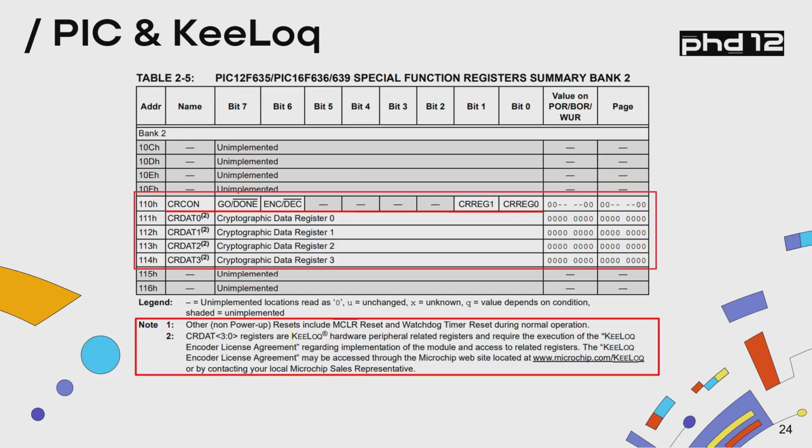So I started reading the specs. I was wondering, well, AES is often done at software level. What about keylock? Is it there at software level as well? So I was looking for it, and I realized that there were 5 registers associated with keylock. So it's pretty easy to see what 2 bits do. They choose the mode of encryption versus decryption, and to start encryption.